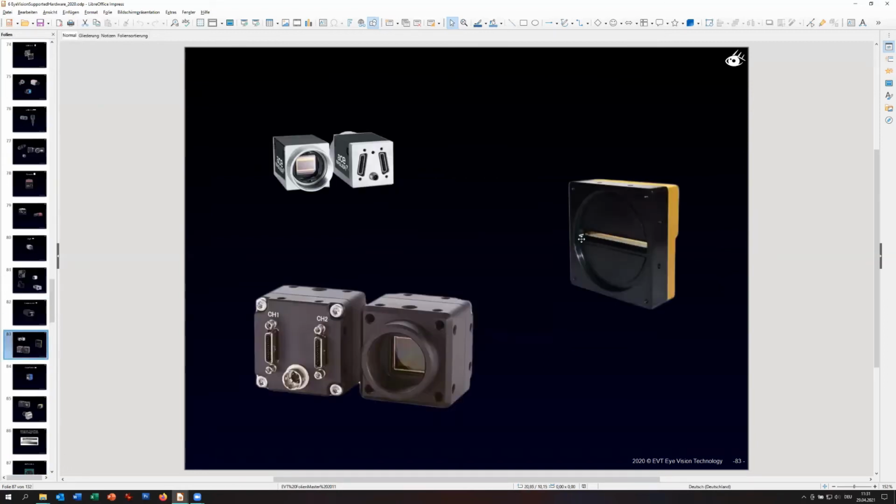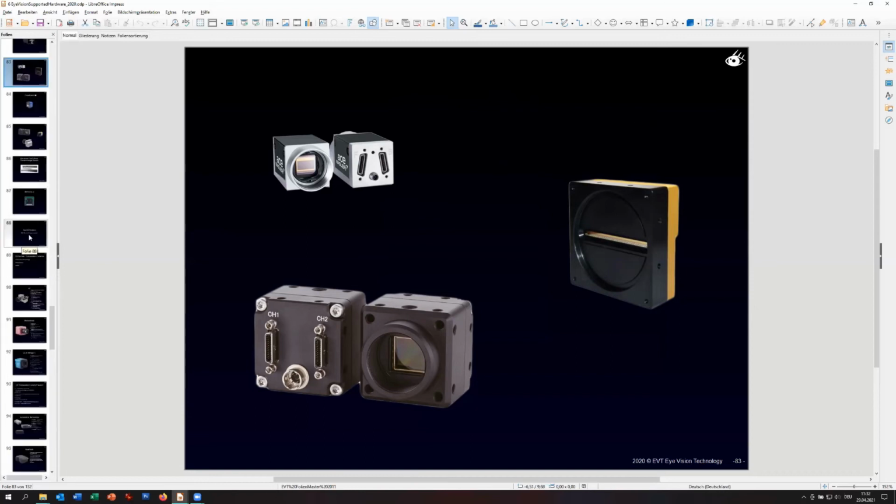Here we see also these line scan cameras. Of course, line scan cameras are especially interesting for really high-speed data transfer, not always. So you find many line scan cameras with the CoaXPress or Camera Link interface, but as I mentioned, with GigE and 10 GigE, you could also make these line scan solutions based on the standard interface. So yes, this was a short overview about the hardware.